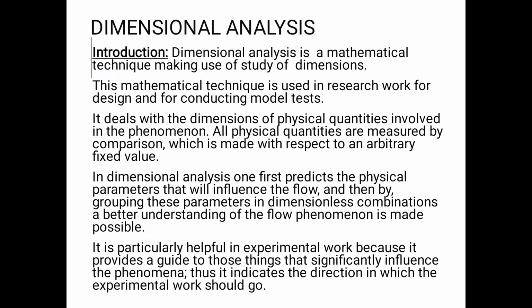In dimension analysis, one first predicts the physical parameters that will influence the flow, and then by grouping these parameters in dimensionless combination, a better understanding of flow phenomenon is made possible. It is particularly helpful in experimental work because it provides a guide to those things that significantly influence the phenomena. Thus, it indicates the direction in which the experimental work should go.